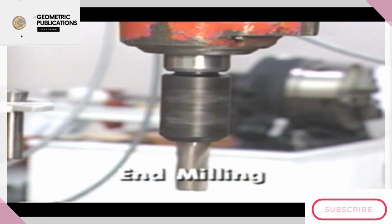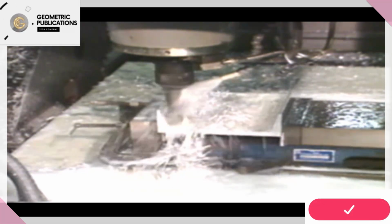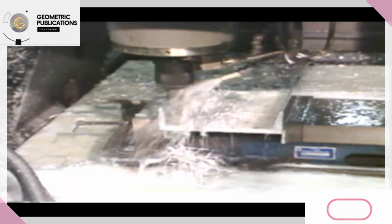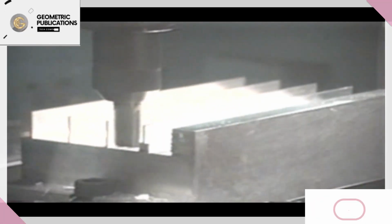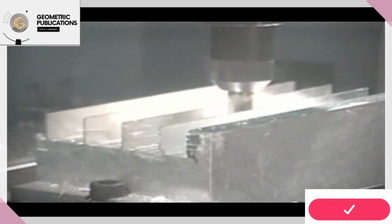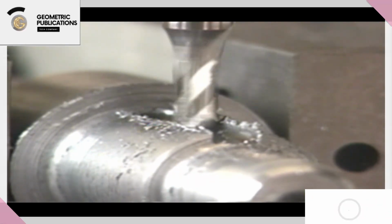End mill cutters are round shank tools with cutting edges on their periphery and end. The axis of rotation is perpendicular to the surface produced by the end of the tool. Its size is measured by diameter and cutting depth capability. Since end mills cut more with the teeth on their periphery than with the teeth at their end, they are susceptible to lateral forces. This makes them subject to deflection, which reduces the accuracy of the piece milled and can lead to tool breakage. Short, shallow slots are often done with end mills.